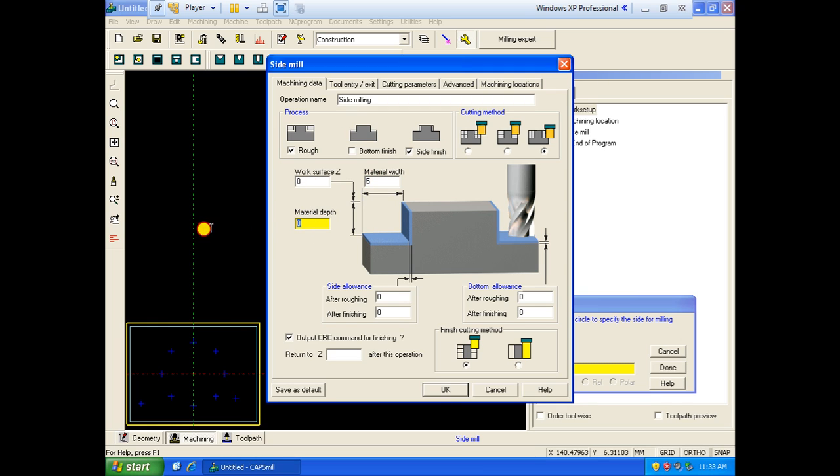What depth do we need to remove? Completely the whole depth, 70 mm, right? You can even take more, there will be no problem, because the depth of this part is only 70. It should just be more than what we actually require. If we require 70, you can take 72 or 75. The remaining residue attached at the bottom will then be completely removed if you take the maximum depth of cut. If you get confused, don't worry, just take 70 also. The depth of cut we require is 70 only.